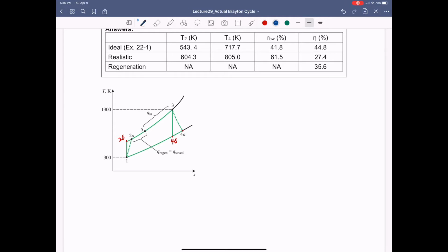So with that being said, how can you calculate the exit temperature of the compressor and the exit temperature of the turbine? What it means is: what is the temperature at 2A and what is the temperature at 4A. What we know is the equation of the compressor efficiency, which is given as h2S minus h1 over h2A minus h1. Always remember the compressor work for the ideal case is smaller than the actual case. So that is what we can write.